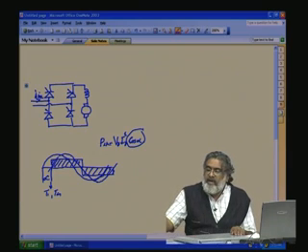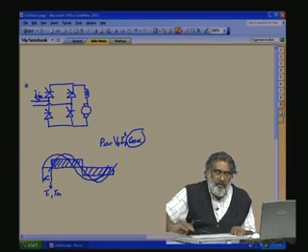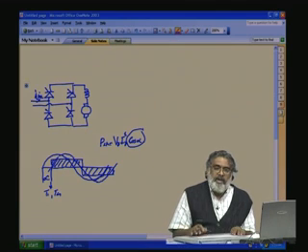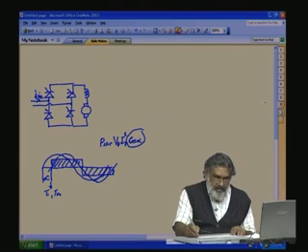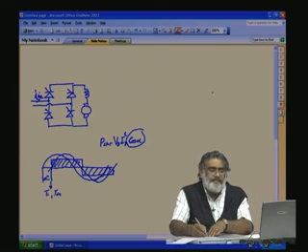The semi controlled converters are used when we don't want negative DC controlled voltages at the output. We only want the output voltage to vary from 0 to positive. Then we will be using only the semi controlled converter. That means 2 thyristors are controlled. What is the advantage of that one? We can have a saving on the gate drive circuit, and cost can be reduced.